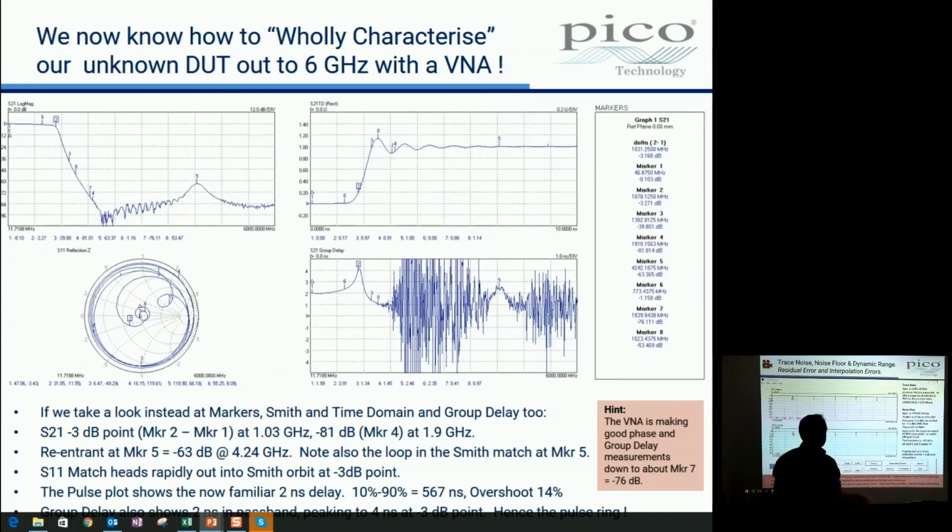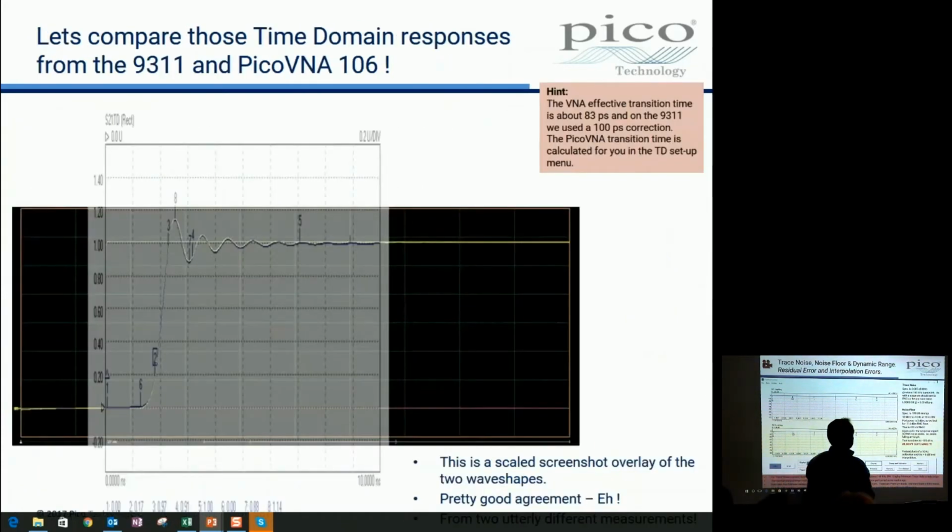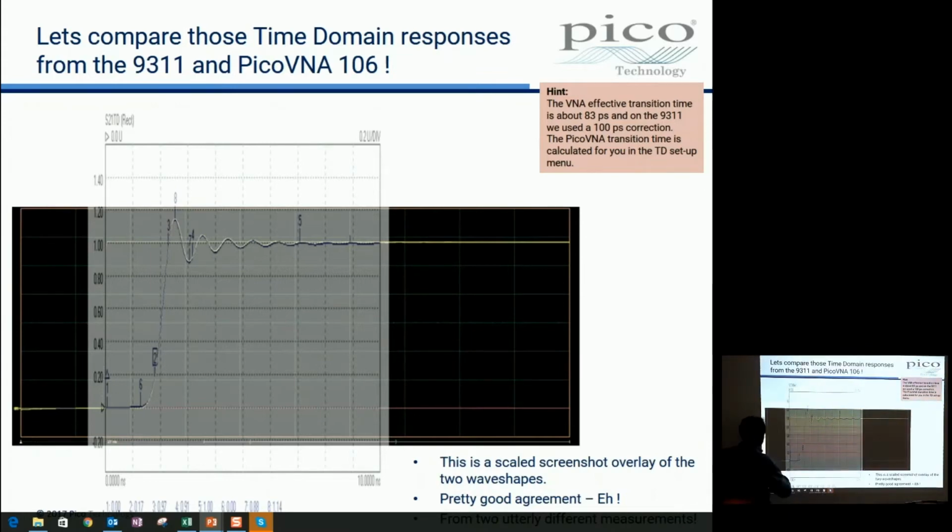So the spec is an RMS spec, but the noise will be seen on the screen as 6 times if it were a scope. Yeah, more or less the same with a VNA. The noise you're going to see at the bottom, it's not peak-to-peak noise, it's peak noise. Yeah, on the VNA.